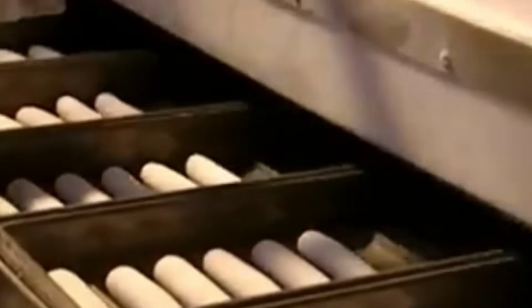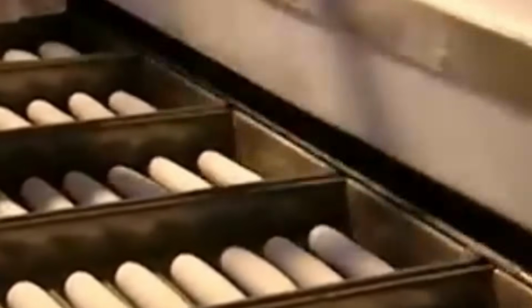A set of guide rollers gently flattens the dough again. Then curling belts begin to shape it, rolling the mass inward to form a tight spiral that will become the loaf's interior structure. Pressure plates calibrate tension precisely, ensuring the outer skin of the dough wraps around the inner layers tightly enough to support rise, but not so tight that the loaf bursts during baking. Once molded, the loaves drop gently into metal baking pans, moving along a wide belt.